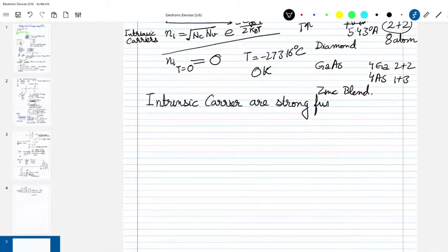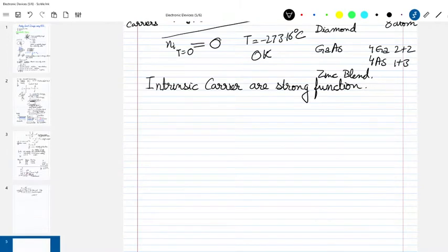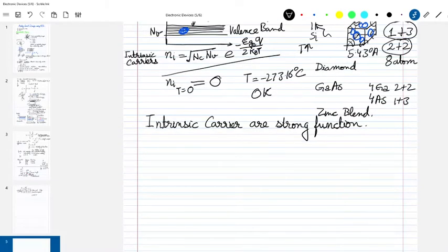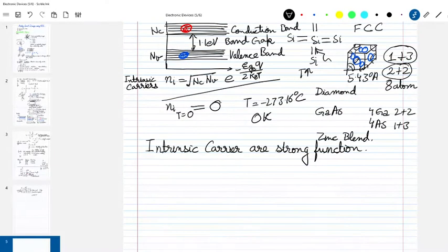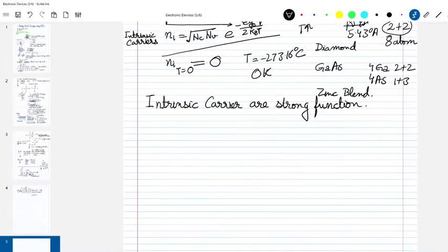Now this is a problem, right? The problem goes like this. If you want to make a certain circuit using only intrinsic semiconductor, the purest form of semiconductor which has only electron-hole pairs which are a function of temperature, and you design the circuit for one geographic location where temperature is like 25 degrees, and then take it to another location where the temperature is minus 40 degrees, then the temperature dependency is so high that the circuits are not going to behave properly, right?